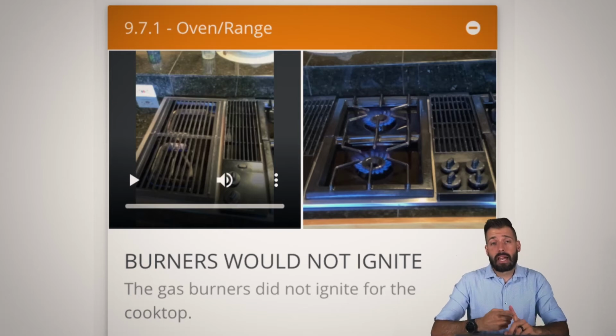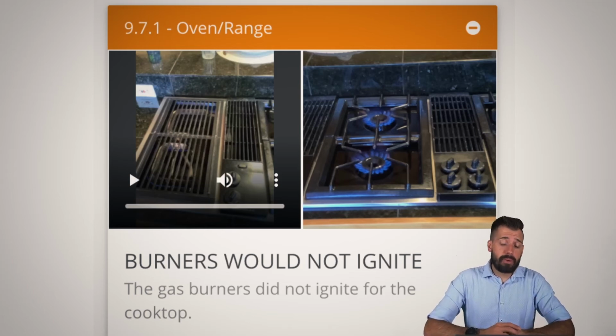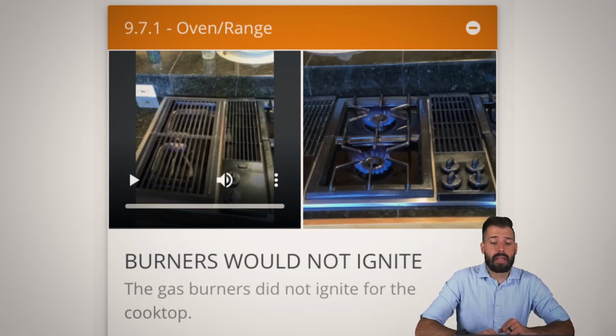And so then that means the igniter may not work, and that also just means that the gas is not being directed in a way that'll allow it to burn effectively. So it could be that we need to replace some components, it could be that the appliance is bad, or it could just be that whoever reinstalled the things after cleaning didn't put them back together the way they're supposed to. So the next thing is water supply.